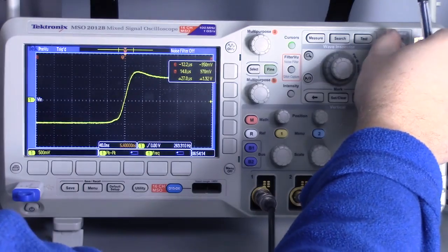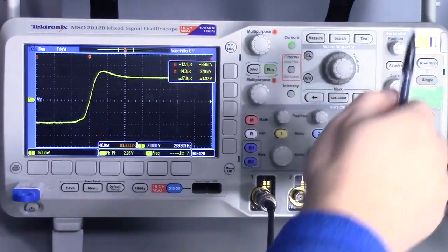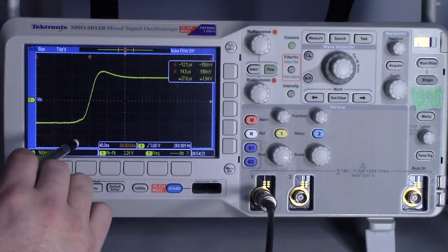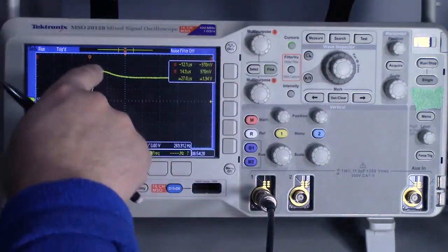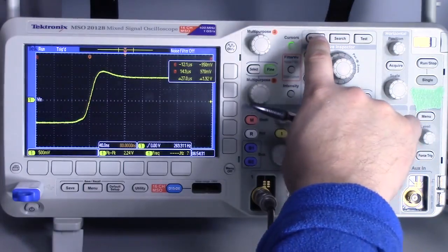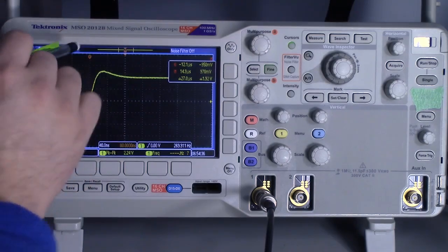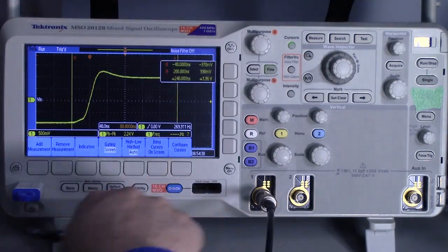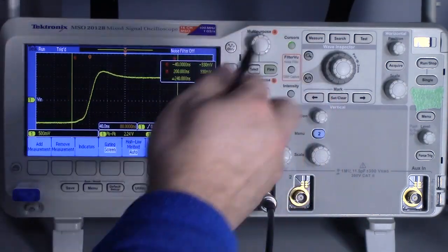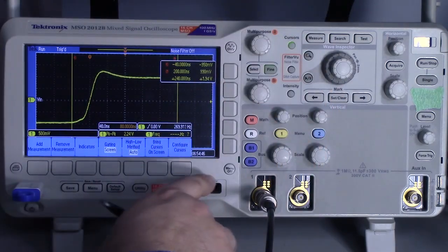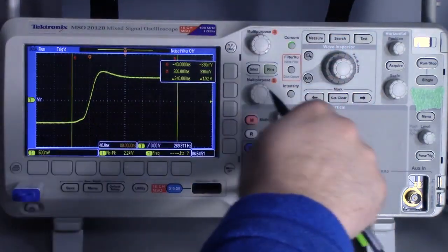Now, I want to measure the rise time of the square waveform of this function generator. I can bring the cursors. Oh, it already was up. Another thing that is useful to know is that you can also look up here. That tells you that the cursors are off screen. Now you can just press that button, and that will bring the cursors onto the screen. A lot of times, if you press the cursors button, you don't know where they are. That's just a quick way of doing it, instead of looking up here and then turning the knob until you get there.